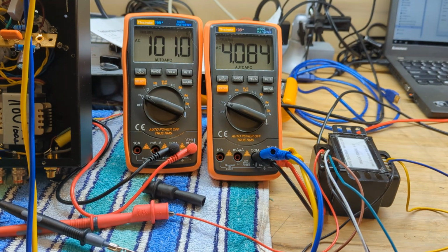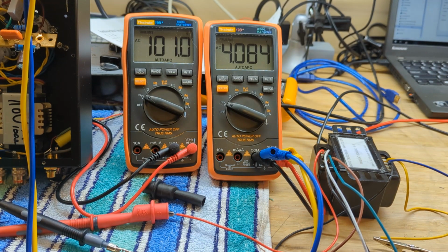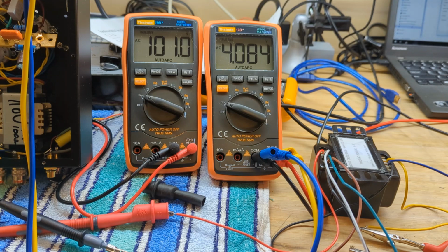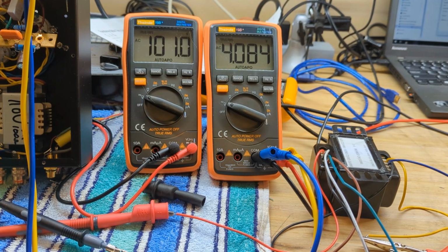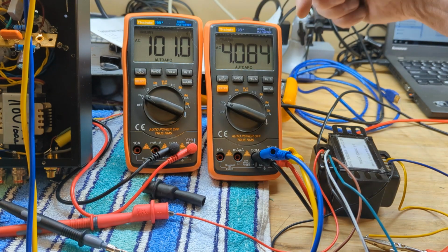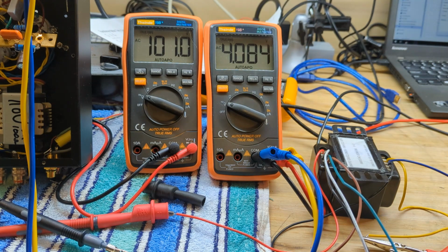And for an input right here, I've got a kind of close frame, so it's hard to see the parts. So I'm going to inject a voltage into the 8 ohms. I put 4 volts into the 8 ohm. I'm using a signal generator this time, not my Variac setup, for a little better resolution or a little control of the input. And I put about 4 volts in, and I got 110 volts out on the 8 ohm load.